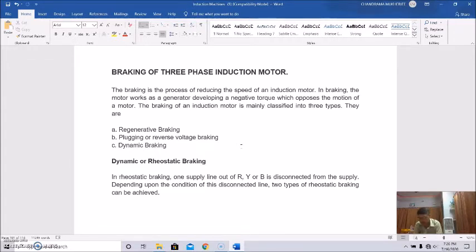We have discussed multiple stator winding, consequent pole changing method, pole amplitude modulation method, rotor rheostat control by operating two motors in cascade, then injecting an EMF in the rotor circuit, that is Kramer systems, Scherbius systems, and also we have talked about the slip power recovery scheme, that is static Kramer system and static Scherbius system, etc.